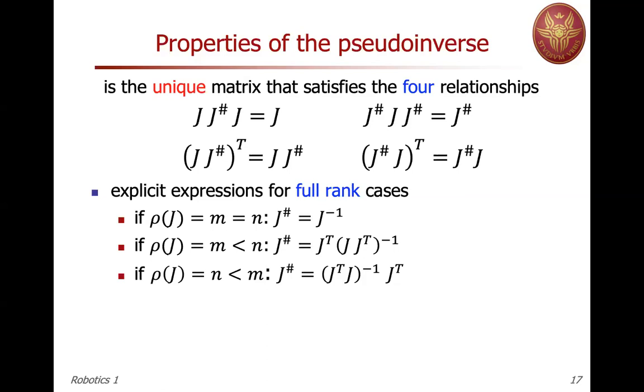The other interesting case is related to the damped least squares, when you have redundancy, so more joints, more degrees of freedom than task variables, so M is strictly less than N, but you have a full rank J. So you can cover any desired task velocity V, which is M-dimensional, because of the full rankness. So you are not in a singular situation, even if the robot is non-square, so the Jacobian is non-square.